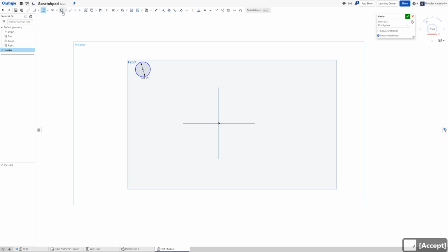They'll start trying to sketch out here. They might put their mounting holes somewhere out here, right? Say I want 6 mounting holes. One of the things I'm using here is called implicit constraints. That's when I mouse over this and then I move it out there and can see that orange line.